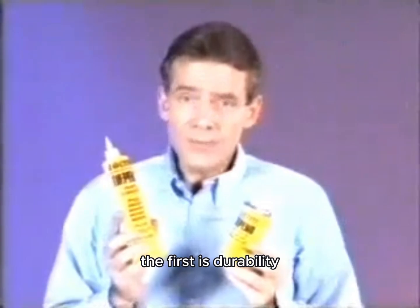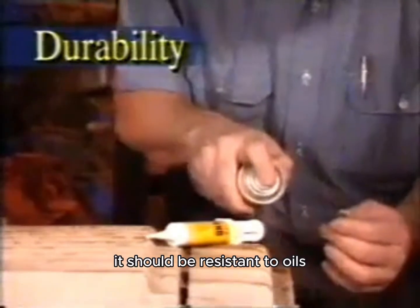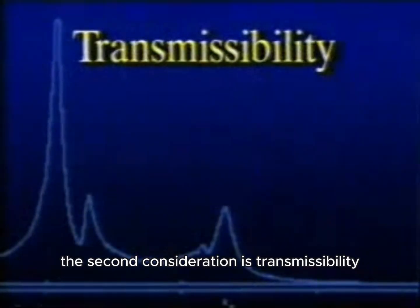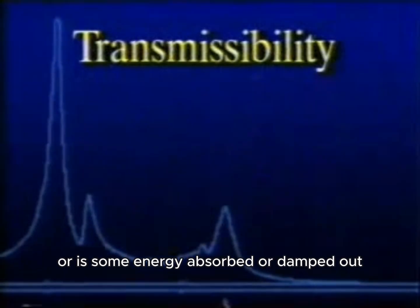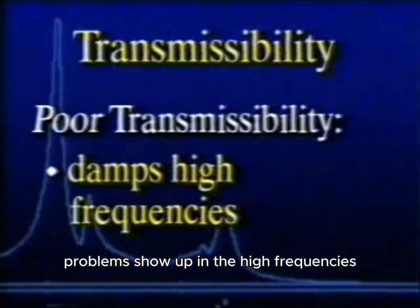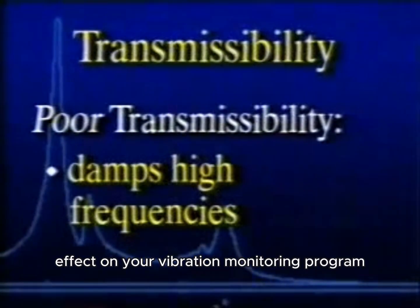The first is durability. It should hold to most surfaces well without losing its grip over time. It should be resistant to oils, temperature changes, and process chemicals. The second consideration is transmissibility. Does the adhesive transmit the energy through it to the sensor, or is some energy absorbed or damped out? Too much damping will cause high frequencies to be unnoticed. Since most severe problems show up in the high frequencies, damped signals could have a detrimental effect on your vibration monitoring program.